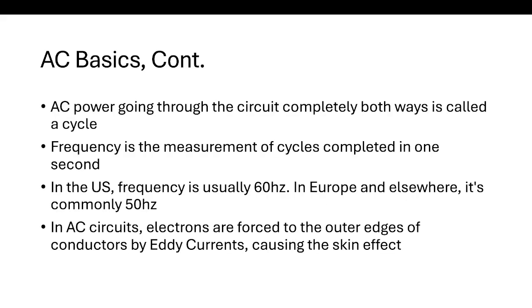So AC power going through a circuit completely, like going out and returning, is called a cycle. Now, the frequency of a circuit is the measurement of the amount of cycles completed in 1 second. The common frequency within the US is 60 hertz, but in other parts of the world it's commonly 50 hertz.